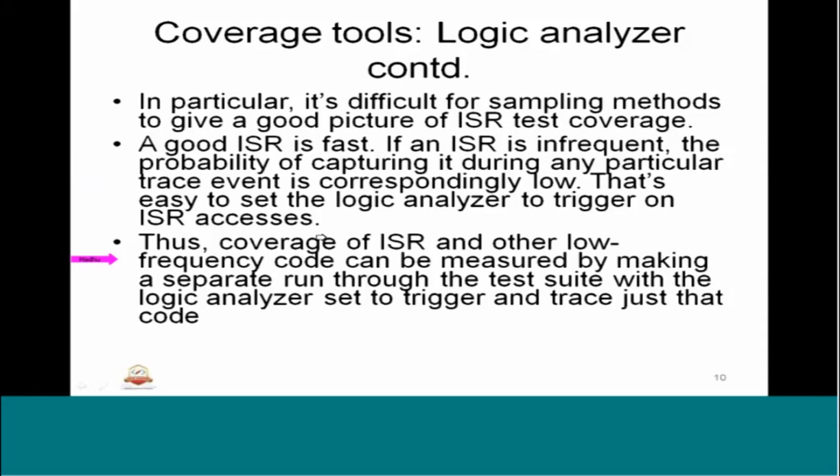So what can happen is we focus only on the piece of software that is part of the ISR. Since ISRs are very fast and frequently happening within the system, and the system may have complexity in terms of a larger number of ISRs, the best thing to do with the logic analyzer is to comment out the rest of the code and focus only on the ISR.